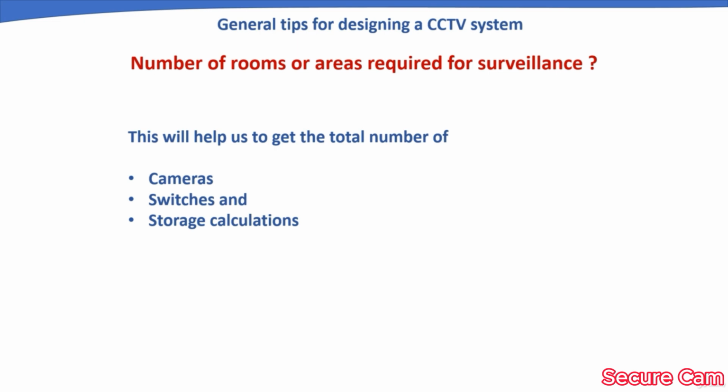Number of rooms or areas required for surveillance. This will help us to get the total number of cameras, switches and storage calculations. This plays a very critical role while designing a CCTV system. Every CCTV system designer should have this information.